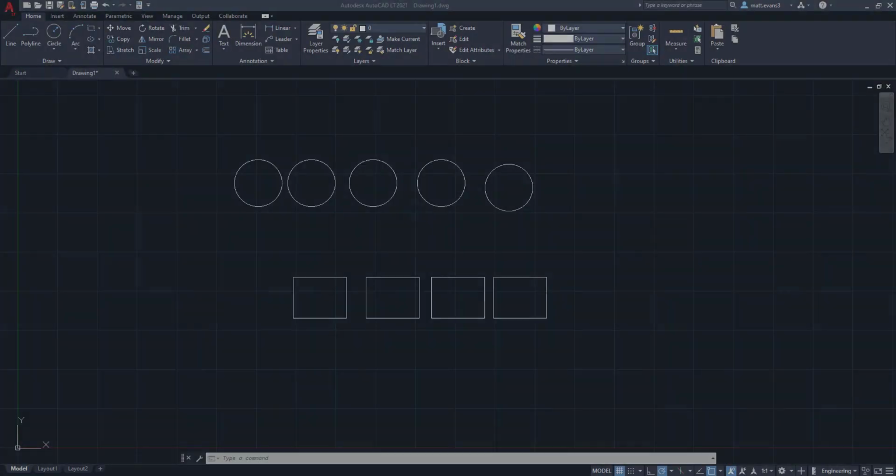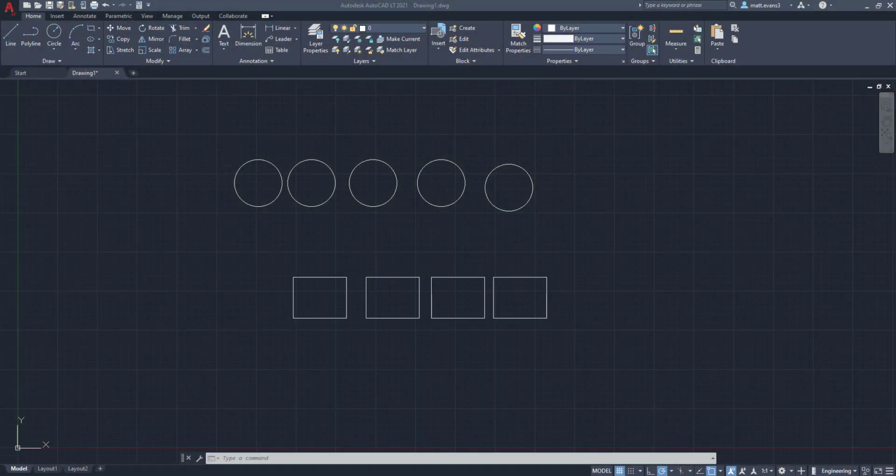Alright, so before we get into how to create a group, let's go over a high-level definition and kind of what a group is versus a block. So a group is exactly what it sounds like. It's a group of objects, and with that group of objects, you may want to take it and rotate it, copy it, mirror it. You can really do a lot of stuff with a group of objects. And for a block, it's something that you kind of just want to use occasionally and insert it directly into a drawing. So a group is more of objects that are in a drawing that you want to manipulate. A block is objects that you want to be able to insert into your drawing that might be kind of high level or intricate, and you just want to be able to insert them right away.